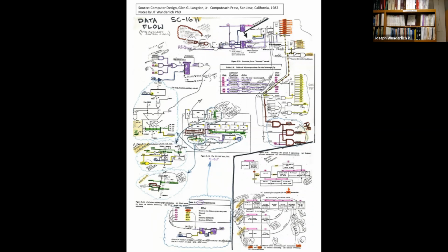And you can look at some of the other things going on there. They show the states too. There's a finite state machine that corresponds to this and how it is implemented, the sequencing of things. Then as we scroll down a little bit, on the left side, in the middle of the page, is the ALU, the arithmetic logic unit. You can see the different functions coming in from the right in green there, the summing and anding.